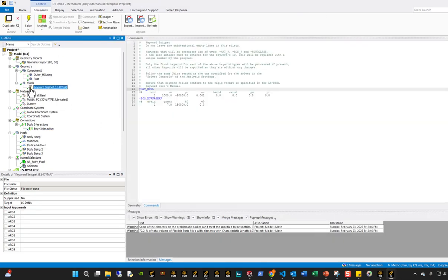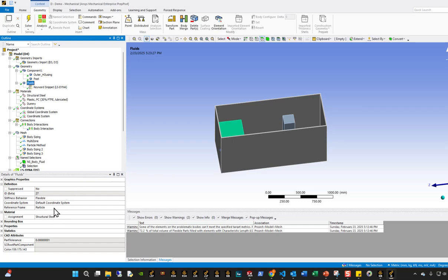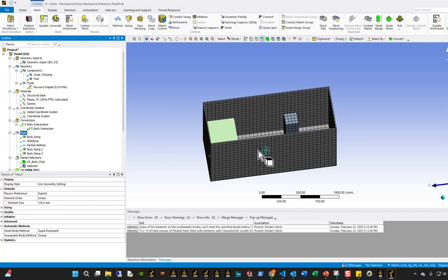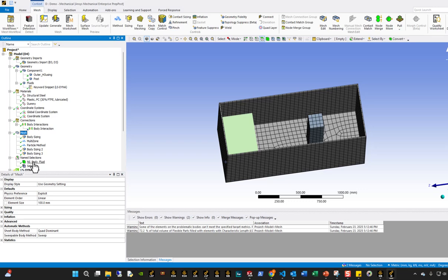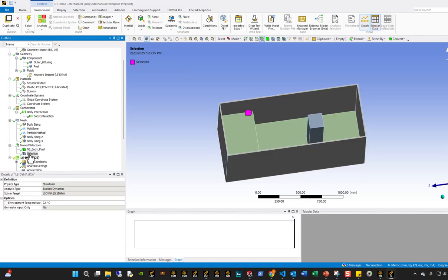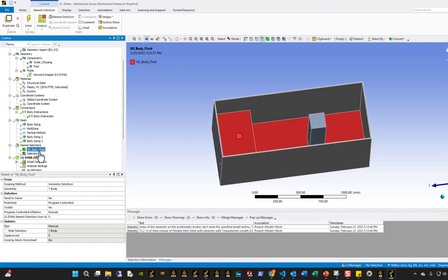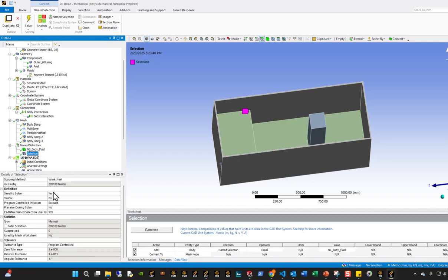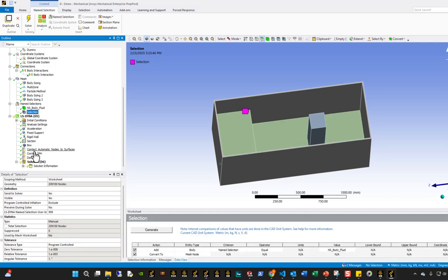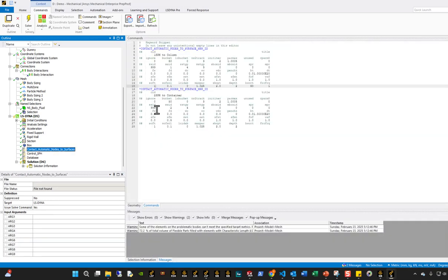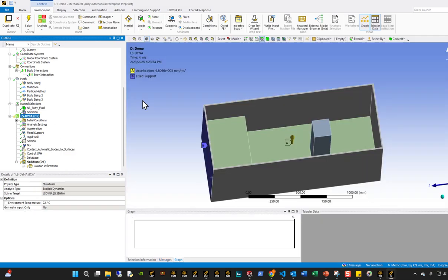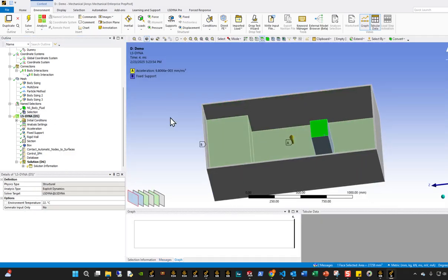We set up the fluid material for the fluids. We set a reference to a particle that allows us to mesh this with a particle. We're going to convert the particle into a node selection set, converted from a body name selection. This node set is going to be defined with a 999 ID. The set ID is going to be converted into a contact automatic card that allows set ID 999 to see body 1 and body 2, which are the housing and the post respectively.